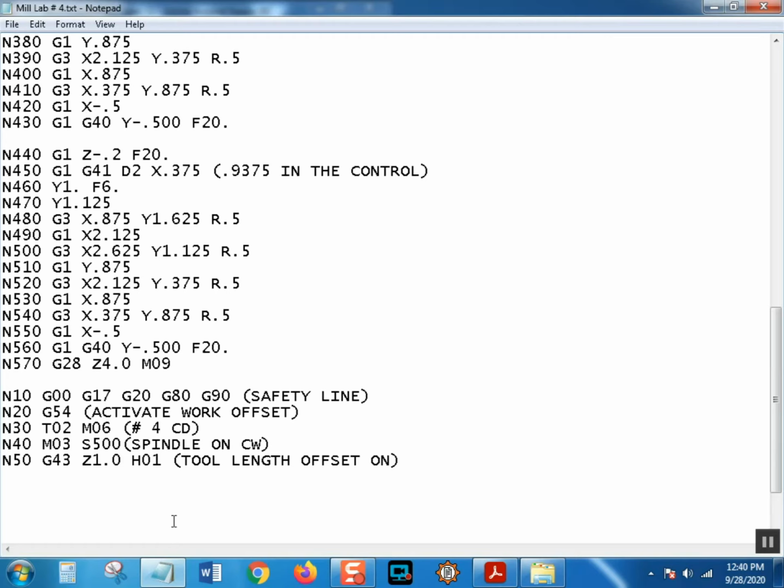Now, how fast do we run center drills? You can do an RPM calculation for the tip. Different size center drills come from 0 all the way up to 6, 0 being an incredibly small center drill, and a number 6 being a very large center drill. If you don't know what a center drill is, it is merely a drill that starts a hole for a drill to follow. Basically, we use them because it makes very accurate positioning. Some spot drills will do the same thing. We'll talk about spot drills later on. There is some controversy about spot drills versus center drills as far as accuracy of location goes. We're not going to get into that right here. You can have that debate someplace else. Please don't have it here.